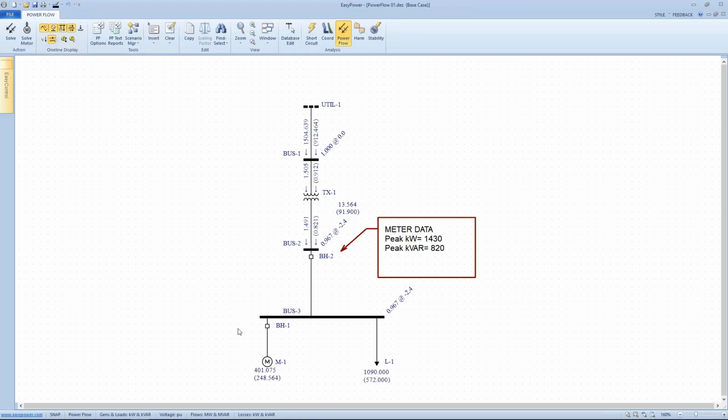And we can project that both in real and reactive power, as well as current, kVA and power factor. We can look at the transformer taps, voltage drops, in which case we're looking for voltage drop basically caused by the loss, and we find the same thing across cables.